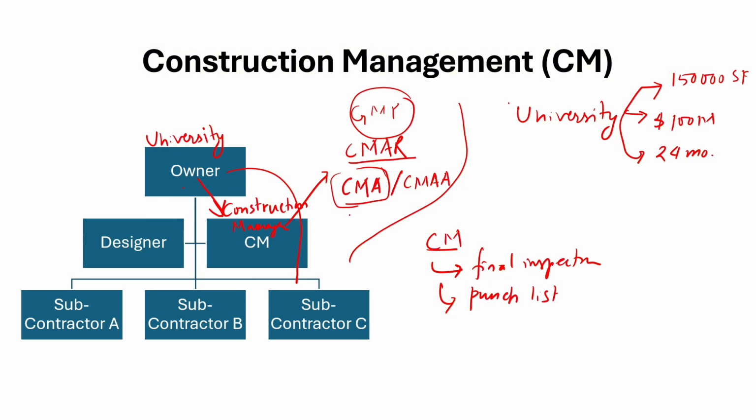And another approach would be construction management as agent, CMA. In this, the construction manager serves purely as an advisor to the owner and does not assume financial risk for the project. Here, the owner holds all the contracts with designers and contractors.